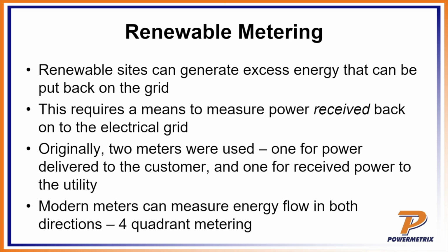Once again, with solid-state metering, the solid-state meter can do that by itself most of the time. The modern meters can be programmed really to do that any way you want. They can have either 2 registers, one for the received energy and one for the delivered energy. They can have even yet another register for the net, or they can just provide the net as the difference of the 2.